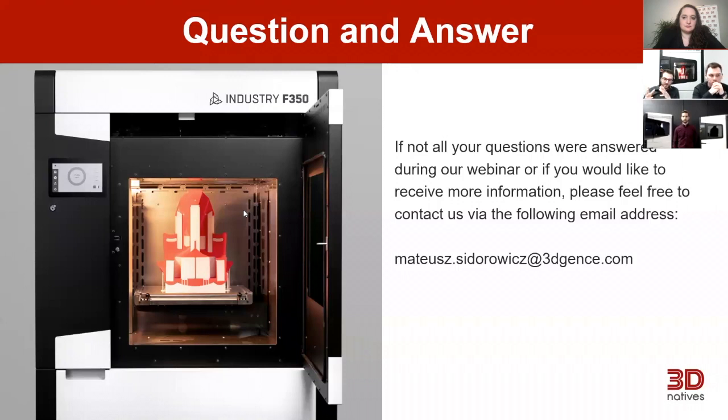I do believe that a lot of different electric tools and closures are actually made of PA glass fiber reinforced, but it also depends on how much fiber load you actually have in the material. If you have, let's say, 5, 7, or maybe even 10%, you will only get some amount of the difference that the fiber actually can make. But the industrial grade loading goes to 30% and possibly even more, and this will greatly affect the performance and the overall characteristics of the material. So that's a very broad question, but hopefully I just scratched the surface there.